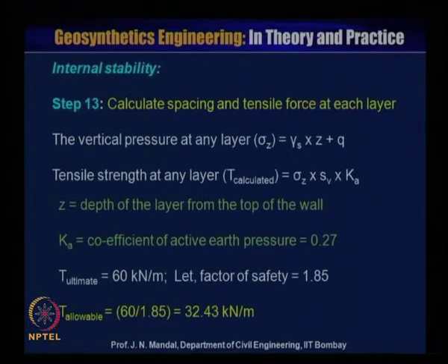The vertical pressure at any layer, sigma z, will be equal to gamma s into z plus q, where q is the surcharge load, gamma s is the unit weight of the soil, and z is the depth of the layer from the top of the wall.